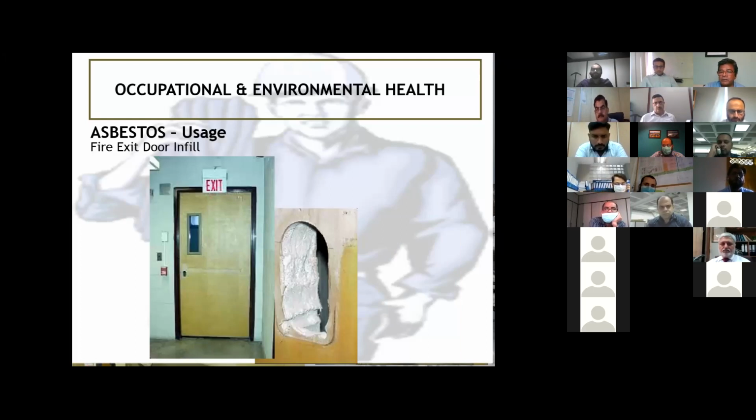Fire-rated doors. Again, some of these doors do have stickers on their side that this contains asbestos. Any door that has a sticker of fire rating, we suspect that there would be this type of infill material that's shown on the right. So you open that lock and we can see this 2 inches or 1 inch thick layer of asbestos infill, because it's a fire rated door.